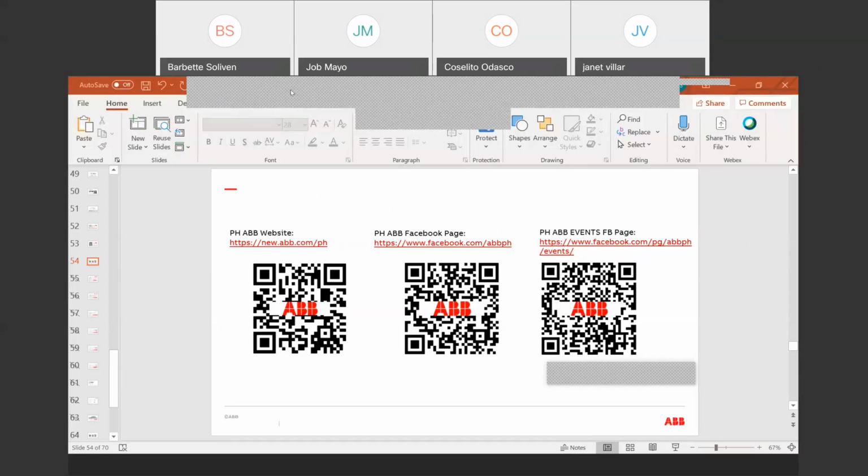So it's referenced on the short circuit breaking capacity of a circuit breaker. You would see in the specifications 100% ICU, which means that the ICU is equal to the ICS. So basically, it just implies that the circuit breaker can be used 100% after a certain fault.